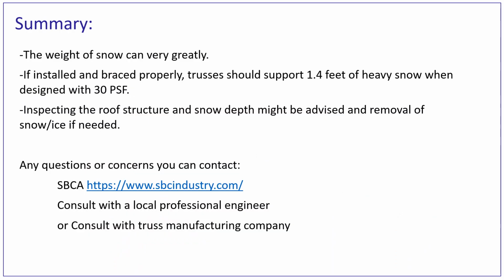In summary, the weight of snow can vary greatly. If installed and braced properly, trusses should be able to support 1.4 feet of heavy snow when designed with 30 pounds per square foot. Inspecting the roof structure and snow depth might be advised, and removal of snow and ice if needed. Any questions or concerns, you can contact SBCA at www.sbcindustry.com, consult a local professional engineer, or consult with your truss manufacturing company. Thank you.